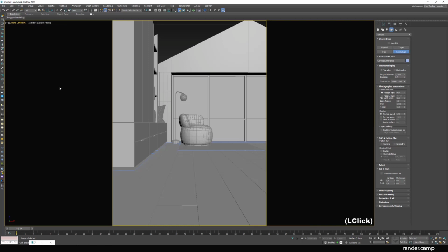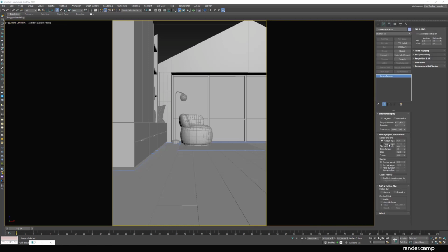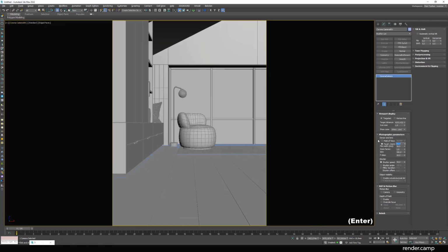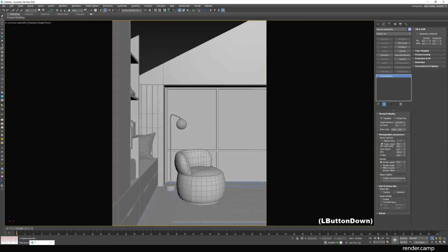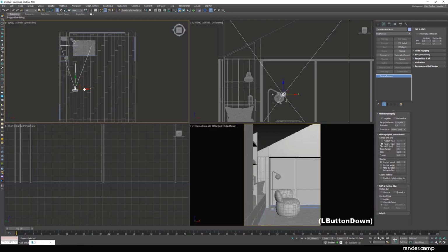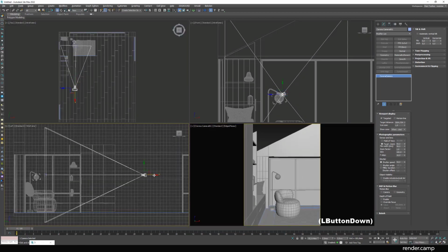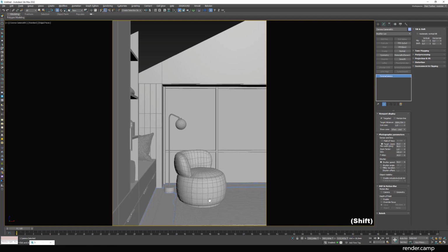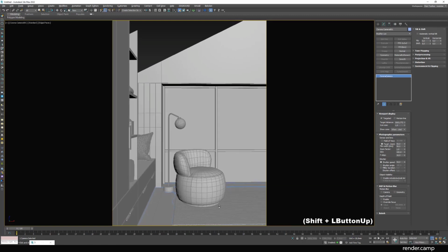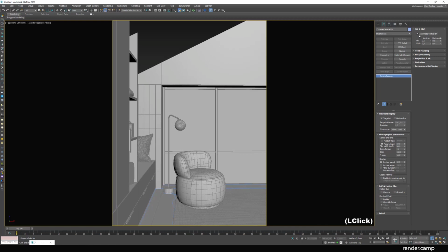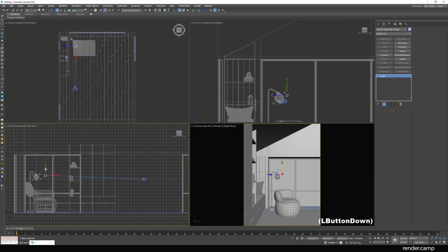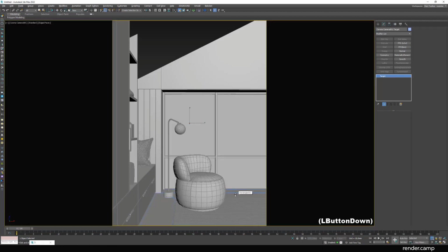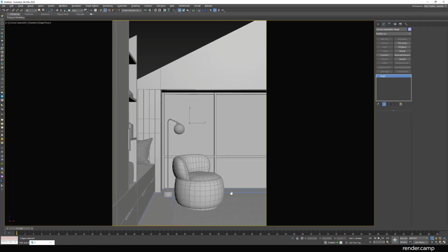Click Camera, select it. Modify tab, select focal millimeters. Set 50. Lift up camera more. Press Alt Z and zoom in. Customize your camera with these movements. Move camera to the left on the top view. Activate automatic vertical tilt, set horizontal 0.02. Put camera a little down, select target and move it. A little more corrections and camera is ready. That's it for today. In the next lesson we'll set up lighting.